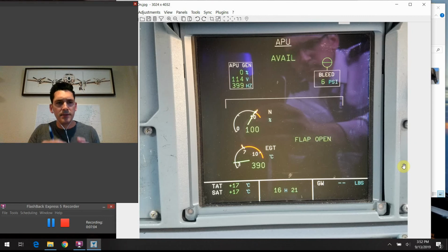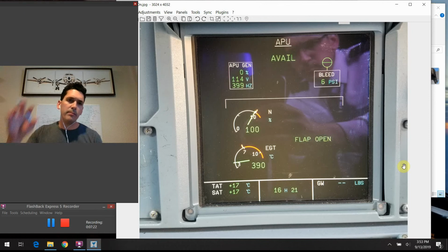There's a time period there where the ground crews haven't had a chance to hook up the outside air and the outside electrics to the airplane. So we still need to have all the systems in the airplane powered. There's a little window of time where the APU will continue to stay up until the ground crew has a chance to get everything plugged into the plane, and at that point we'll bring the APU down if we desire to do so. Those are a few general scenarios about when we're using this normally on the ground.